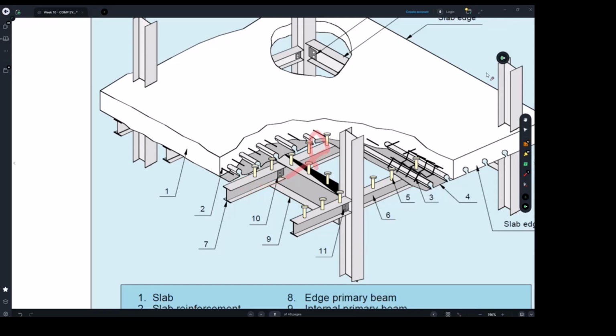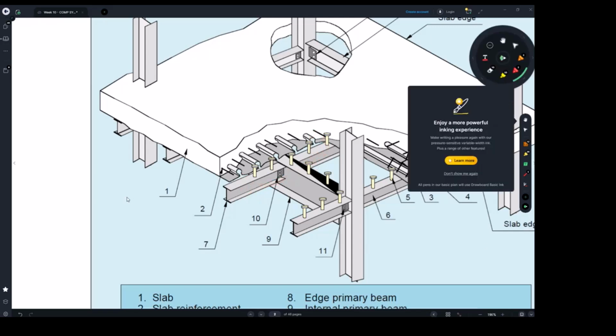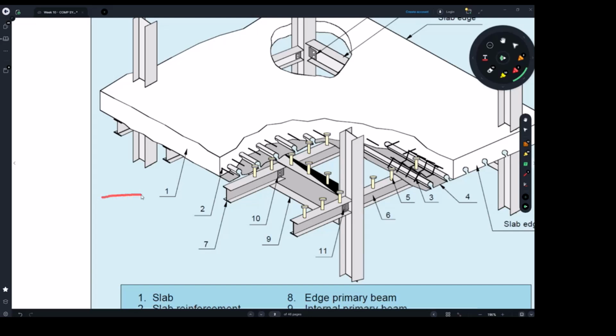If I give you a cross section, like if I cut through here, I will try to draw what's going on there. There is an I section. This is an I section for the steel beam. Then on top of the steel beam, we will be welding what we call shear studs. We have to weld them at full strength to the top. So these are the shear studs. It's up to the engineer, 250, 300, 200 millimeters spacing. And they're going to interlock with the concrete.